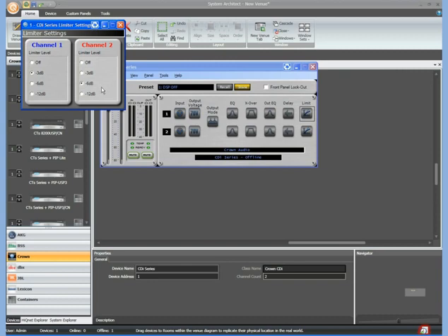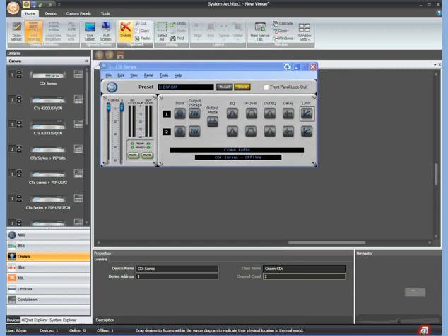The best way to set this is to turn up the music to a reasonable volume, pretty close to clipping, or as loud as you might want to play it. Turn on the limiter, and then back it off one setting from where you can hear it. You could also simply set a -3 dB or a -6 dB point for safety and leave it at that. For most people, -3 dB is a good safe setting. That's the basics of the CDI series.